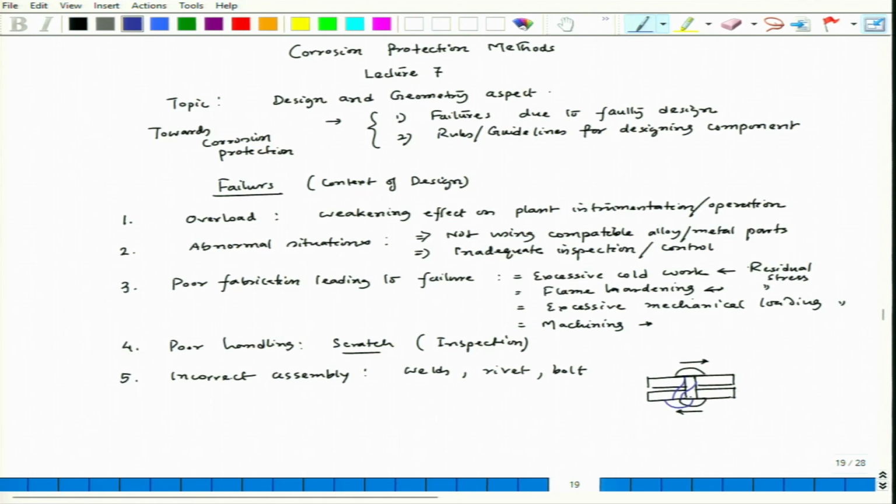Rivet can bend like this, and if this rivet bend is exposed to a corrosive environment, definitely stress corrosion is one of the failure paths. We have to be careful there. And in fact, another part we have to be careful about is the rivet material